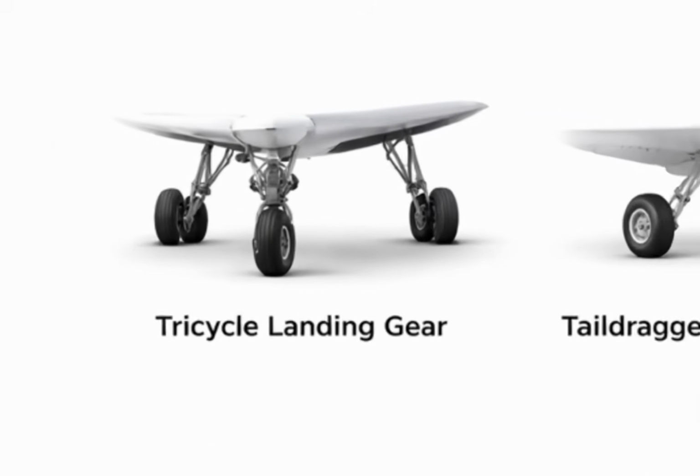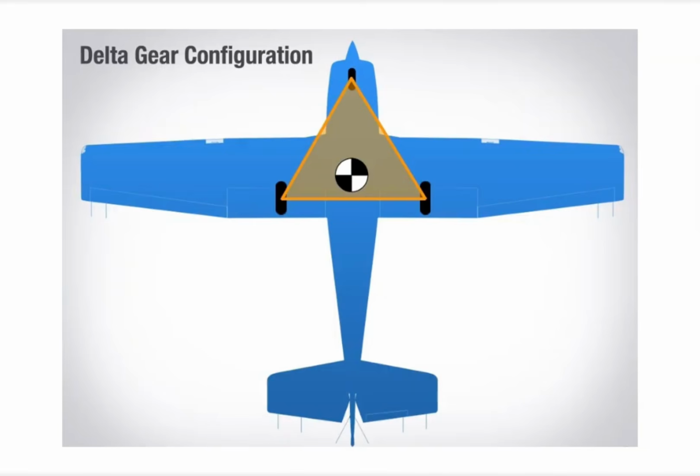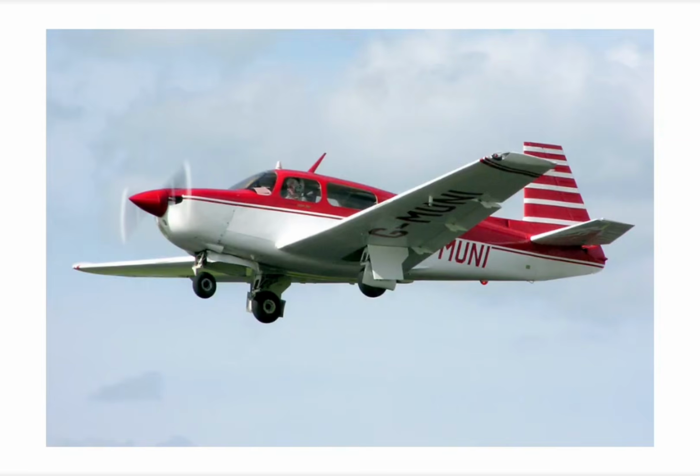Tricycle landing gear. Tricycle landing gear is the most common configuration used on modern airplanes, and it consists of two main wheels located under the wings, or fuselage, and a smaller nose wheel positioned at the front of the aircraft. This design gives the aircraft better stability during takeoff, landing, and taxiing. It also provides improved forward visibility for pilots on the ground, which is why most commercial airliners and modern training aircraft use this landing gear layout.